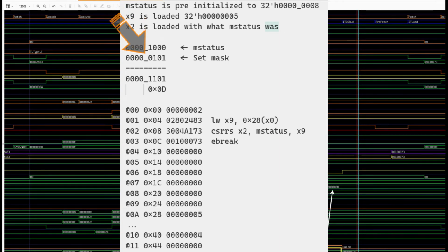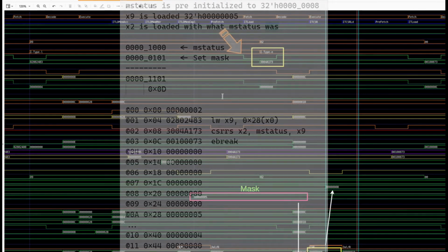So when the instruction executes, it'll set each one of the bits up here with anything that's a 1 down here, which means we get a 1 from the original 1, a 1 that's been set, a 0, nothing changed, and another one was set. That answer is D. So we should see that the status register has D in it when this code runs. I've already set up the simulation. Let's check out the results.